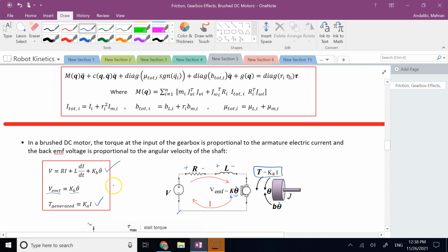Now we can combine these two equations into my original equation from the previous lecture and get more detailed equations of motion, where the input to a robot is really the voltage that you apply to your joints, and the outputs are the q double dot terms. Then of course the integral of them will be q dot and q.